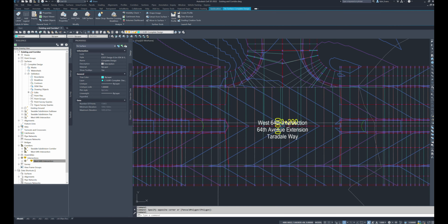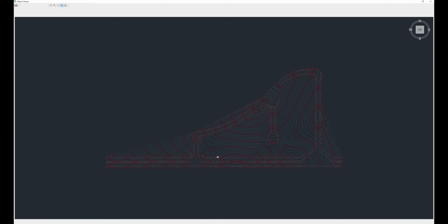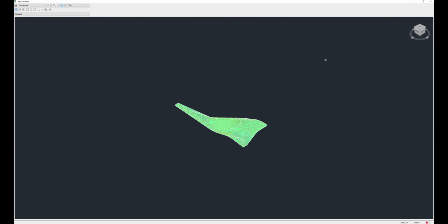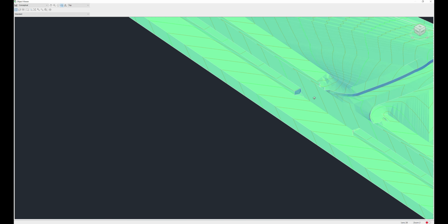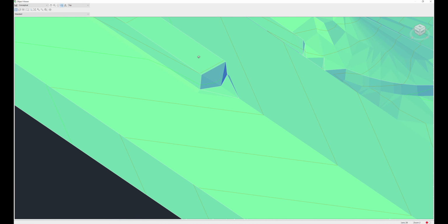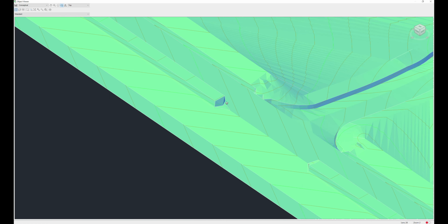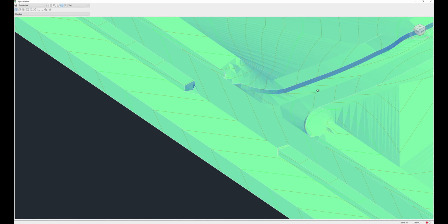And we can see that actually the road here has now tied in. So that 0.13 meter change in elevation is essentially the distance from the top of this median to the top of the road elevation center line. Now we can see that these roads, the primary collector follows through nice and smoothly. We have no bumps. We've got no speed bumps. We haven't changed the elevation of the center line itself because we modified the assembly with the median. We've bumped that up by the 0.13 meters.